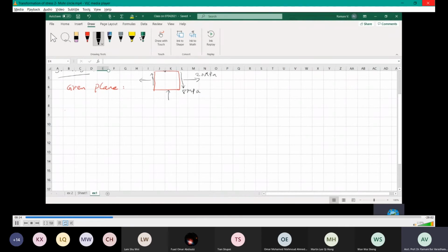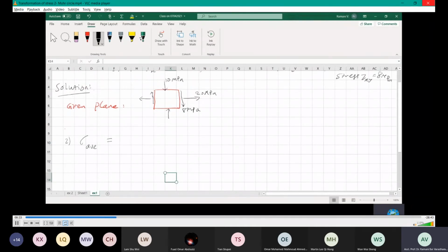The very first step in your solution is, sometimes it's given, if not you draw the free-body diagram, and then second will be to find average stress. Your Mohr circle starts with finding average stress. All these equations are there in the formula sheet. Generally speaking, all of you know that whenever a body is subjected to loading, remember the video I showed last time, it is subjected to compression, tension in the axial direction, and shear along the surfaces or end surfaces, isn't it?